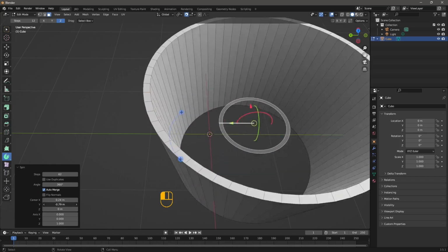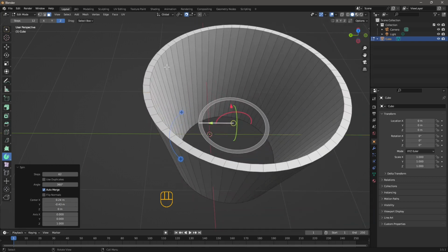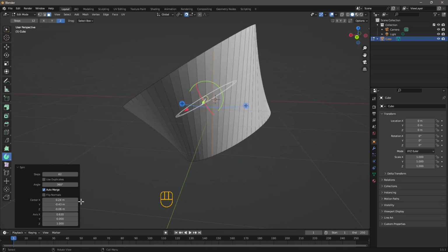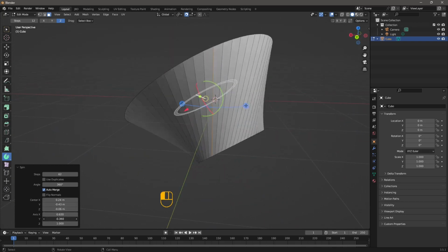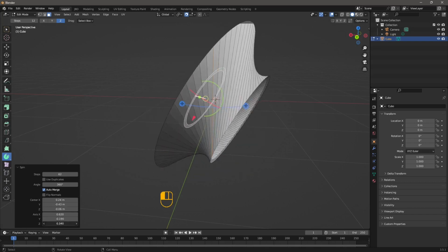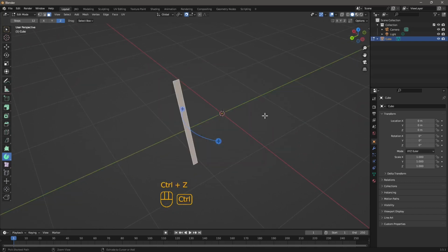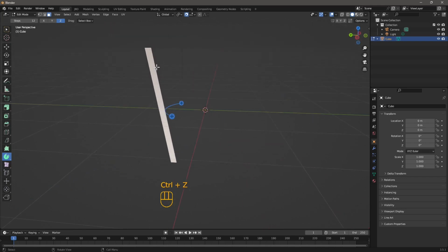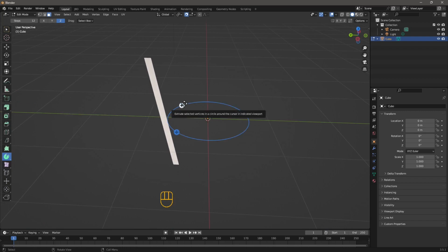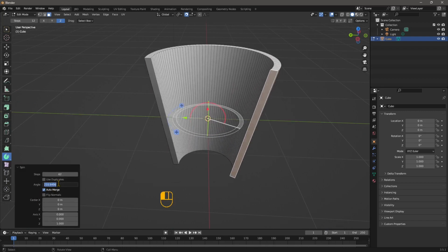So it's making it larger or smaller because that's the path around the axis that the profile is doing, the shape is doing. And you can also try with the axis here. So you can see you can create some really strange results. And you can create rims with this tool and, well, anything that is basically a profile around an axis, you can do it with this tool right here. Now, when you finish, you just say okay, and that's gonna be your object.